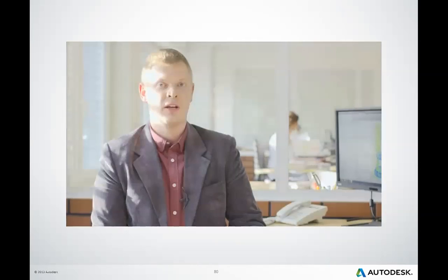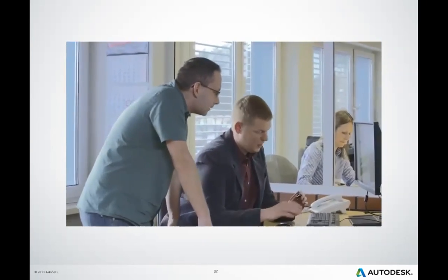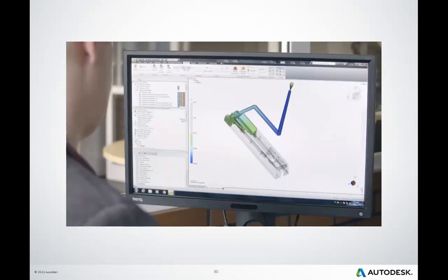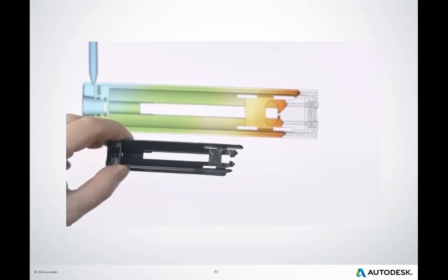Most final part defects have their beginning in the early stage of product development and are usually related to insufficient verification of the design and technology concept. Preventive actions after mold trials often mean costly modification, the necessity to accept some part defects, or in some extreme cases, a change of the mold design. Thanks to Moldflow simulation software, we are able to foresee potential problems related to difficult part geometries and counteract them at the early stage of design.